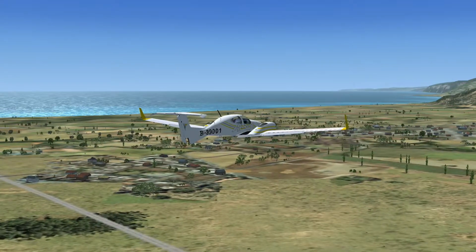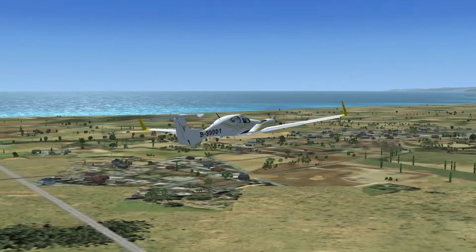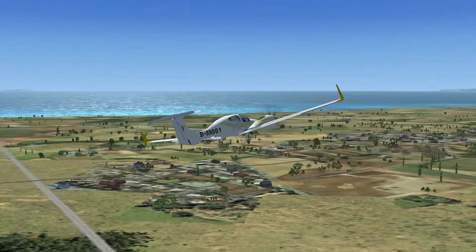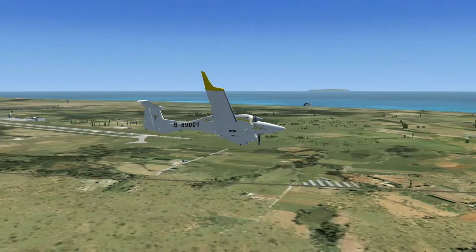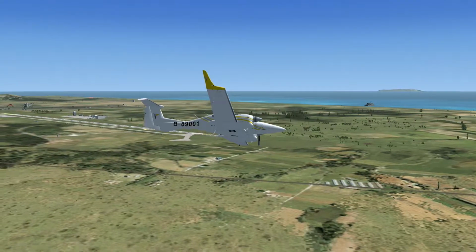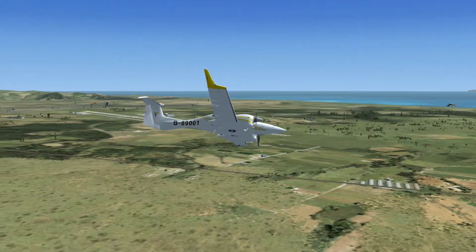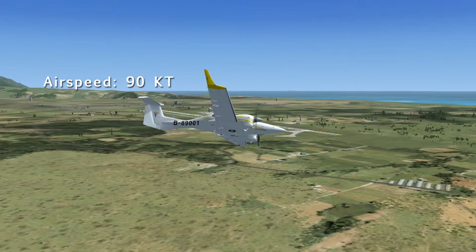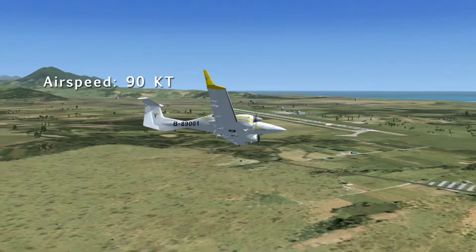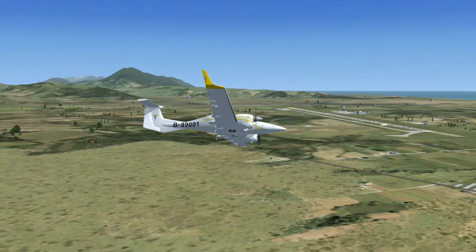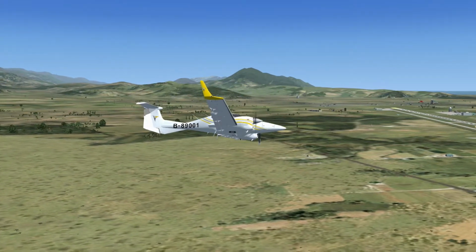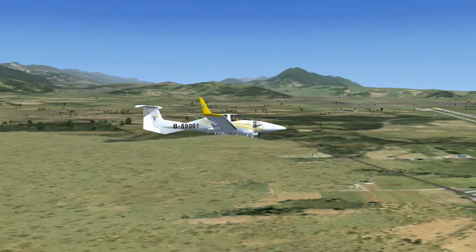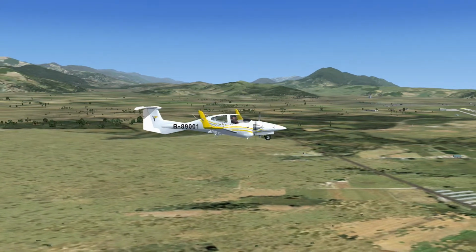Approximately 45 degrees, start turning left, maintaining the coordination of the aircraft and remembering that every time we turn into, we bank into the inoperative engine, VMC will increase. Airspeed on base becomes 90 knots. And when stable on base, we will put the gear handle down.